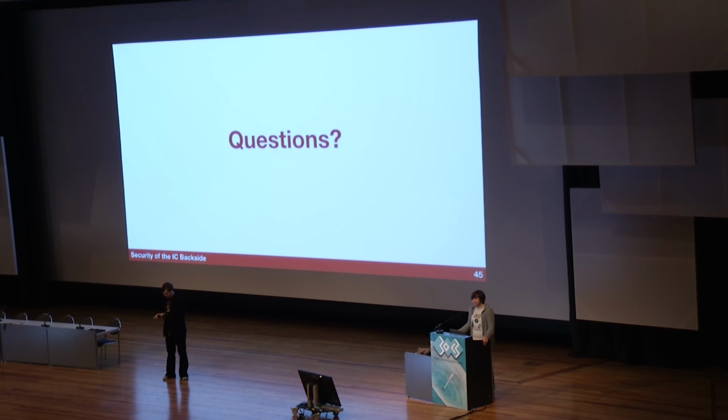Hi, thank you for the talk. I have a detailed question about the SRAM readout with the infrared laser. I was wondering if that worked with the standard amplifier that came with the FAMOS, and whether you needed to probe the device for that, or if that worked on the external leads. No. We were just looking at the supply voltage. So it was literally measuring the current through the supply voltage of the device.